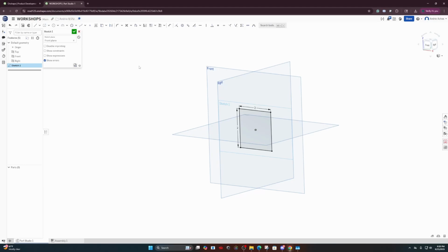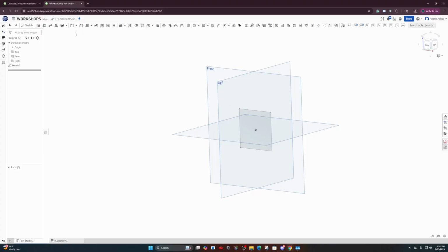So let's now try to make this 2D sketch into a 3D object. So click on the check mark, and let's go press the extrude feature. You can see there's Shift E, that's another shortcut. Okay, now yet again, it's red, that means it's incomplete. And look what's highlighted. It's telling us faces and sketch regions to extrude. Well, guess what? Didn't we already make a sketch?